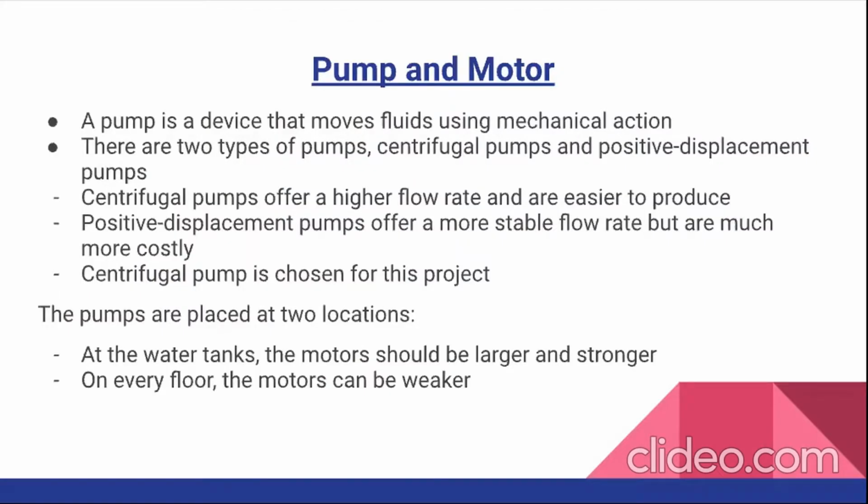Alright, next we have pump and motor. A pump is a device that moves fluids using mechanical action. This action is usually fueled by electrical energy that's been converted to hydraulic energy. There are mainly two types of pumps: centrifugal pumps and positive displacement pumps. Centrifugal pumps offer a higher flow rate and are easier to produce, while positive displacement pumps offer a more stable flow rate but are much more costly.